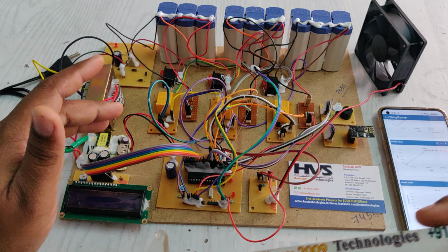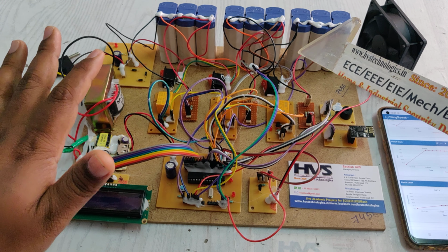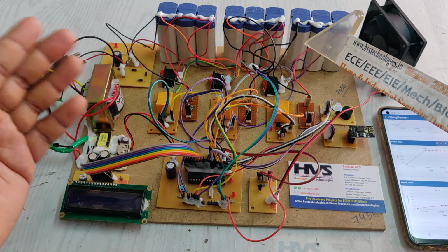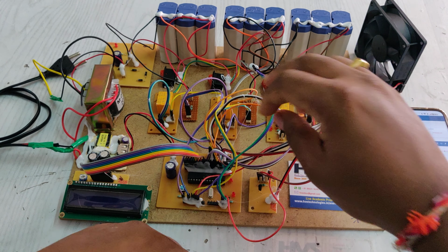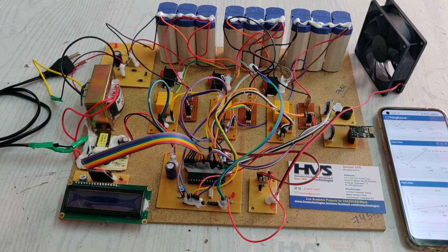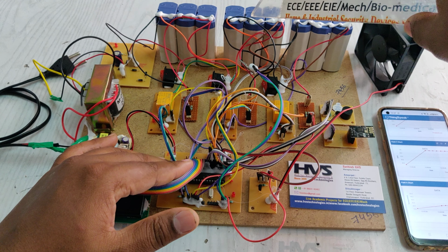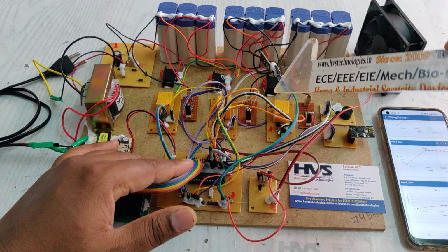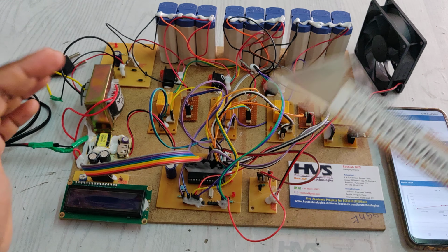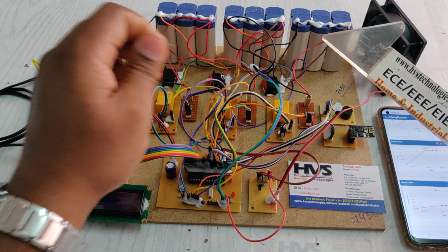Before the demonstration, note that these switches are not a part of the project. Actually, these are switches for charging the battery pack whenever the battery pack voltage is less, for demonstration purposes. Next, these batteries are connected in parallel with the help of these relays whenever a battery voltage is less than the other battery packs, to transfer charge, that means to make active cell balancing.